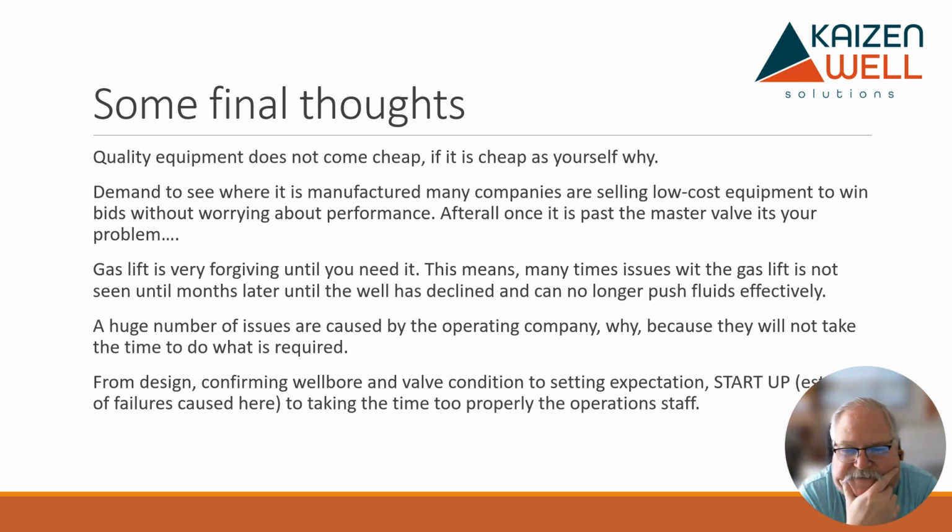You can cut the top valve out of a brand new gas lift system and not realize that you've damaged that system for several months, or until that well's production or pressures have dropped enough that it can't push liquid up to that valve, and then all of a sudden you just stop lifting liquid. And we've seen that happen too, and it's usually done in startup. Guys have damaged it just being impatient, pushing liquids through too fast, all sorts of stuff. The startup is critical in protecting your gas lift.